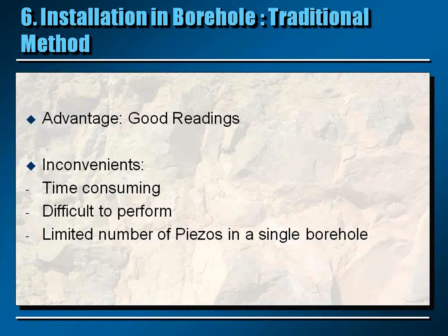So as mentioned here on this slide, the inconvenience of what is called the traditional method of installing the piezometer in boreholes is that this method is time-consuming, difficult to perform, and only a limited number of piezometers can be installed in a single borehole. The important advantage is that when it's properly done, it gives good readings.